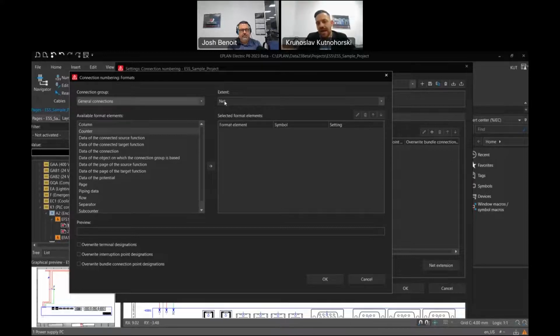The extent is how the numbering should be executed, it means when the counter will change. And here you have the formats for how you would like to number your wires, right?